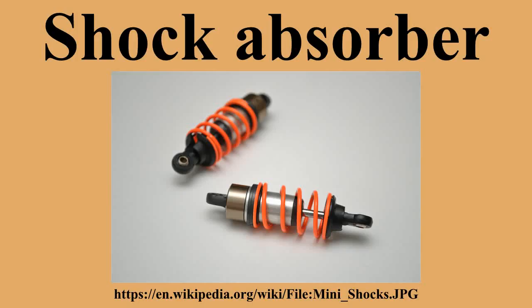Composite hydro-pneumatic suspension combines many suspension elements in a single device: spring action, shock absorption, ride height control, and self-leveling suspension. This combines the advantages of gas compressibility and the ability of hydraulic machinery to apply force multiplication.